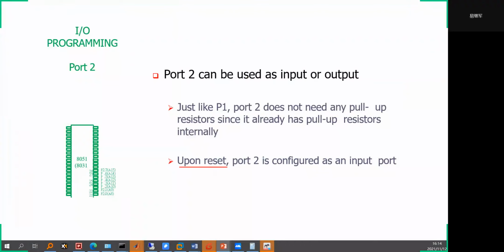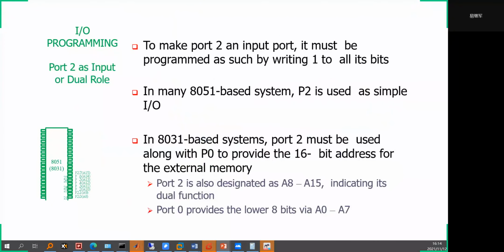Upon reset, P2 is configured as input. To make port 2 an input port, it must be programmed as such by writing 1 to all its bits.